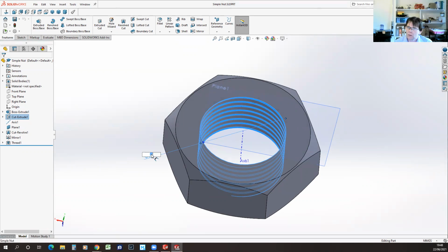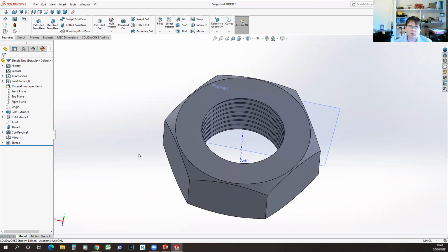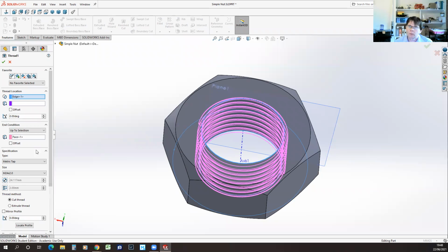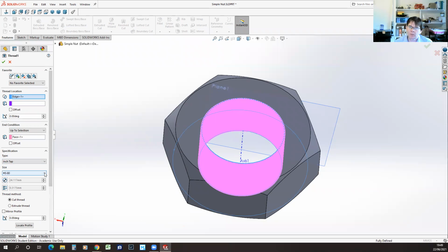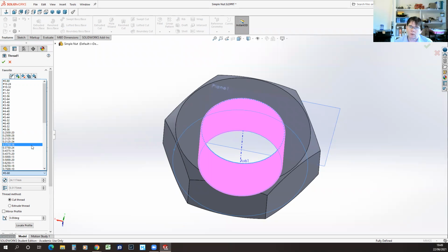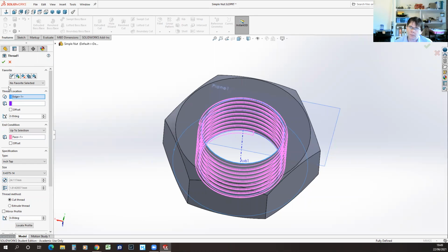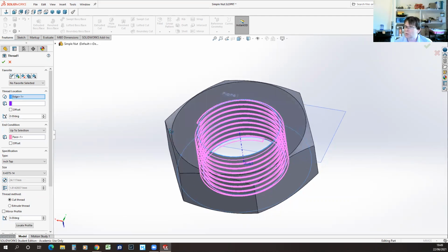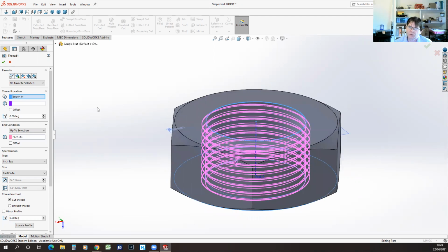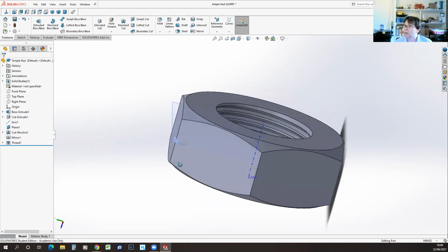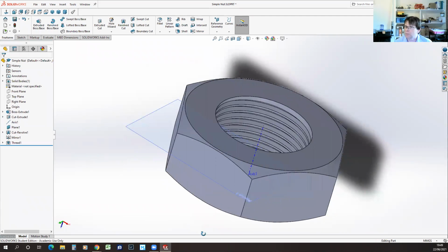Okay, so that was the inner diameter for British Standard pipe for a 3/4 inch. And our thread profile for inch tap was one of the 14 turns per inch threads, the only one in this menu with 14 turns per inch. That was two, there's that one. Just got the right pitch, and that all looks cosmetically about right. So I thought that would be fine, but when I 3D printed it, that did not work, didn't thread onto my standard tap adapter.